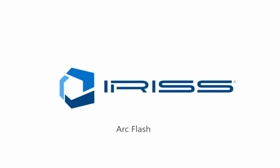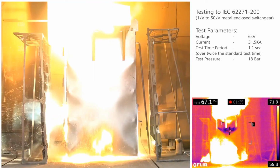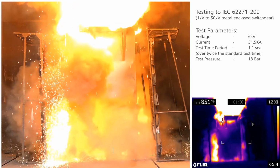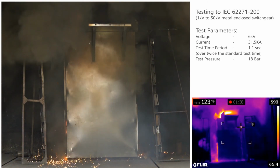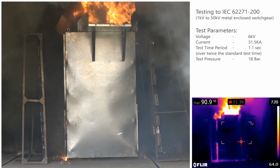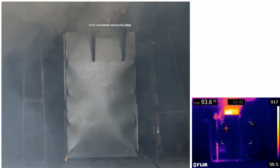So what we did, the test voltage was 6 kV. The test current was 31.5 kA, but the peak current that we saw on the test was actually about 83,000 amps. The test period was for 1.1 seconds, and the overpressure within the box was in excess of 18 bar, because what happened, the instrumentation within the box burnt out at about 18 bar. But a really tough test to pass, and this was what we did to prove the arc containment strengths, not arc resistant, arc containment strengths of our VP and CAP series products in metal clad systems, which would exceed the requirements of any arc resistant system.